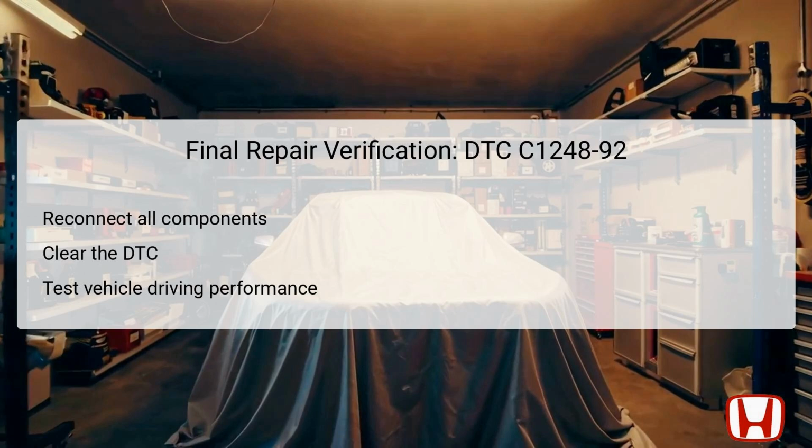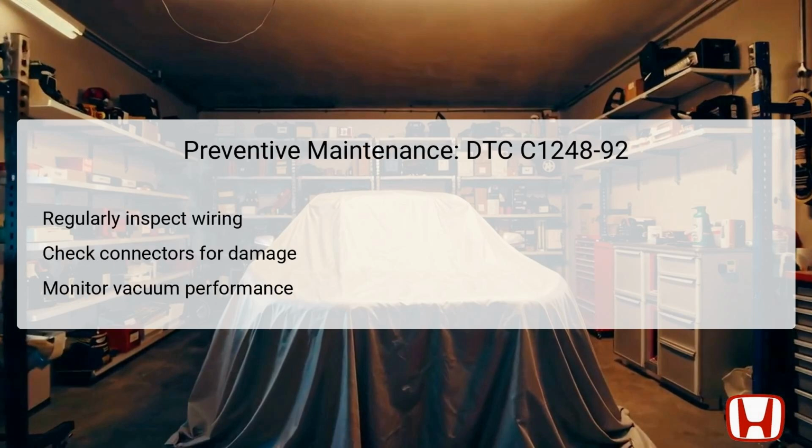To prevent future occurrences of DTC C1248-92, regular maintenance is essential. Start by routinely inspecting the wiring associated with the electric vacuum pump. Any signs of wear or fraying should be addressed immediately. Additionally, check all connectors for physical damage or corrosion, as these can introduce problems in the system's functionality.